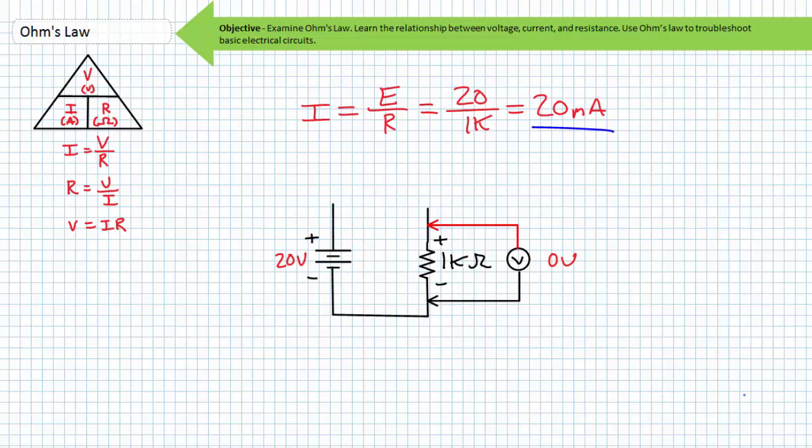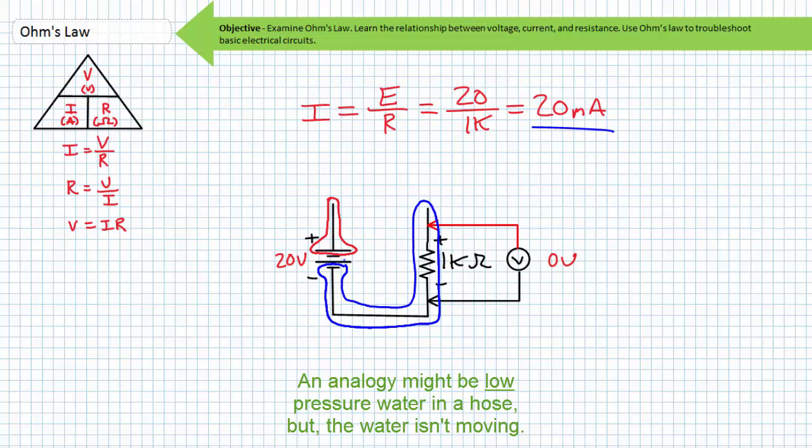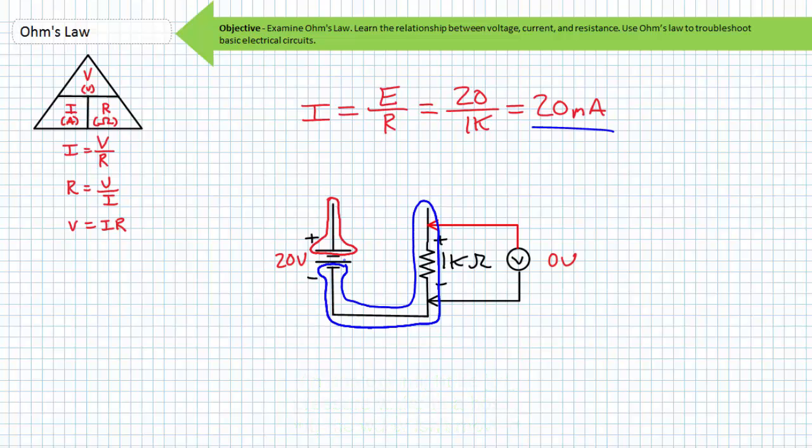The same thing but different for an open between the power supply's positive terminal and the top end of our resistor. The voltage drop again occurs at the open, not across the resistor. Both terminals of the resistor are at the same voltage as the negative terminal of our voltage supply. If there is no voltage differential across these terminals, current will not flow through it. This is like the tube and ball analogy, where the tube is laid flat on the floor. The ball won't roll because there's no differential.